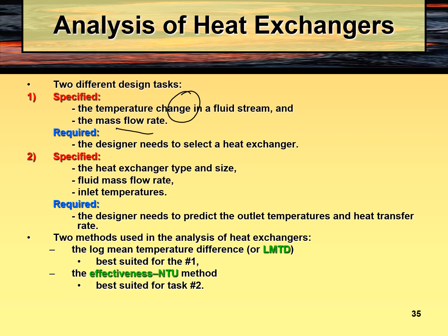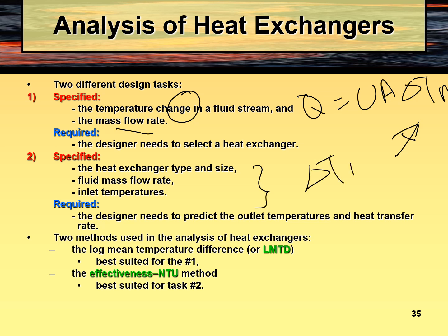If you don't have the temperature difference, you cannot do this. The requirement is Q equals UA delta Tm. To calculate the delta Tm, you need to know delta T1 and delta T2.